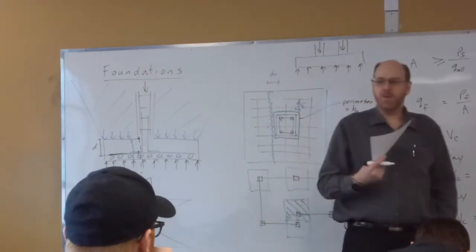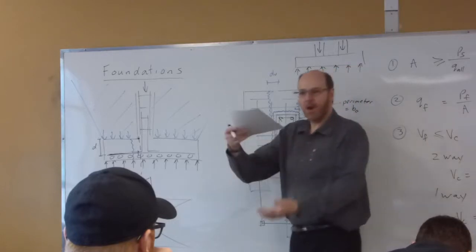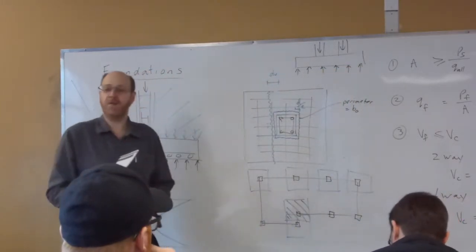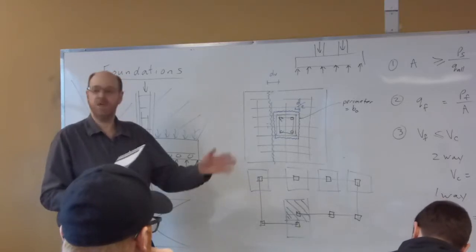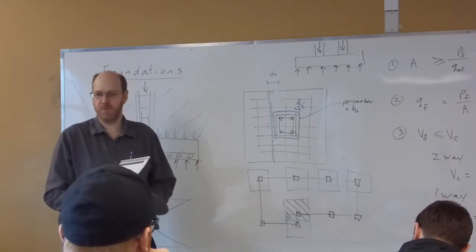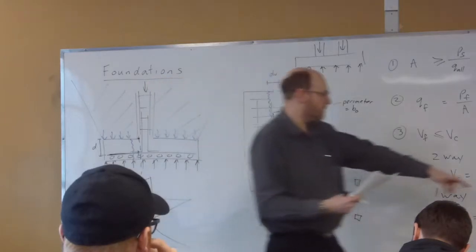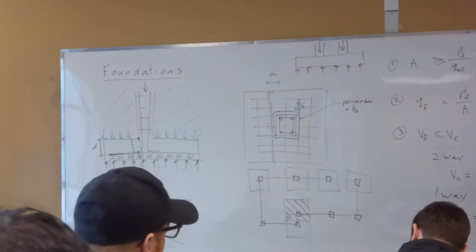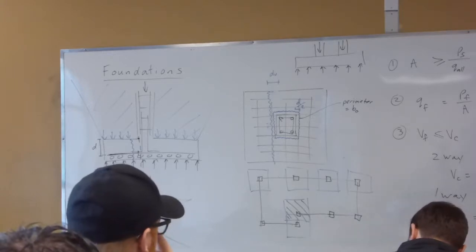So with a large area, a large thickness, and increased cover distances, that's a whole lot of concrete. So why not put the cheapest stuff in? We're not needing it from a strength perspective. So it is quite common to use 25 MPa for our footings. And then 400 MPa is our standard for rebar.